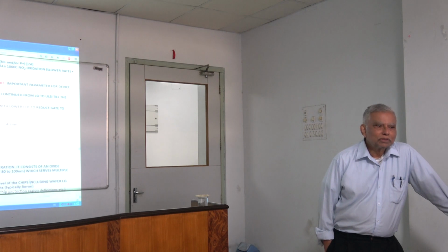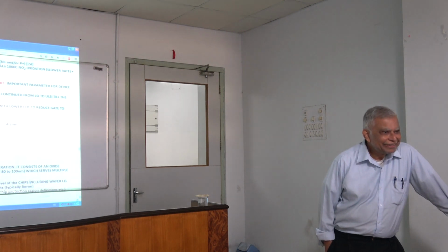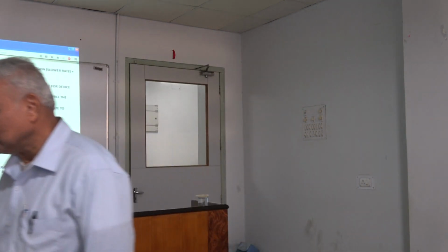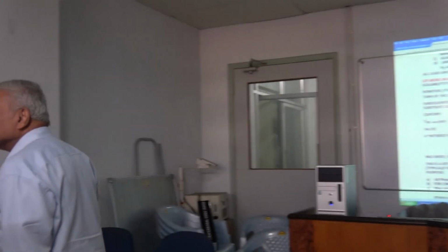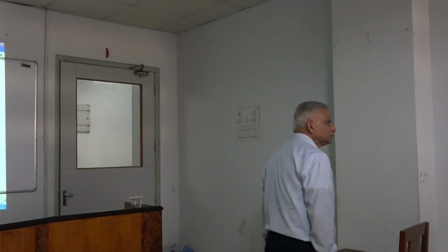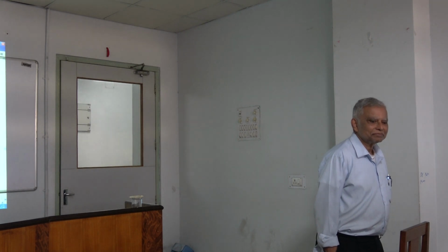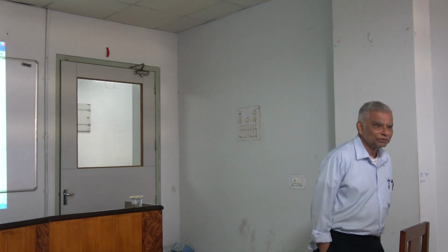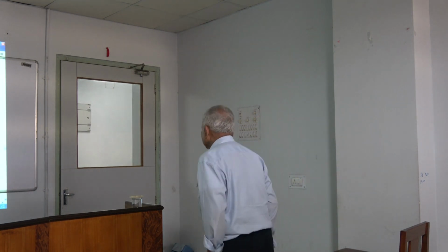So, what was my question? I forgot. What is the EOT of a 10 nanometer FET technology? Even though I may not go into all the details, I want to give you the impression of what exists today. Can anybody guess? Yes, very close to it. It's 1 nanometer. That's the EOT.